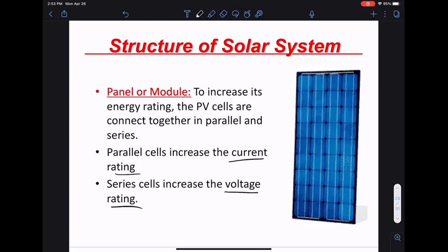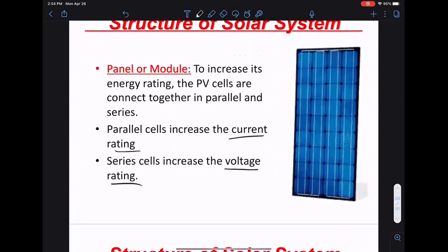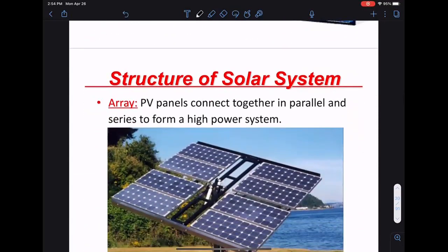Often for those applications, each one has a fairly low voltage and current, and you stack many of them together to create higher voltage and current ratings. Then you can stack the panels or modules in an array to form an even higher voltage and higher power system. These are typical design criteria: you figure out how much each cell can provide, then how many you need to stack together to form an array.